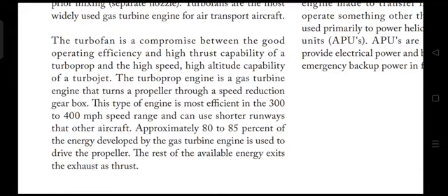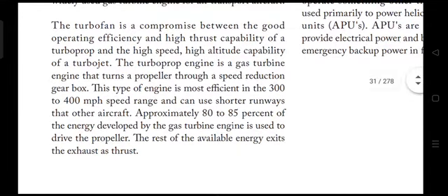These are among the best aircraft for local connectivity, because they don't have to go to a long ceiling altitude. For regional connectivity of 45 minutes to 1 hour, they are the best, because they produce a lot of propulsive efficiency because of that big propeller. Equally, a turbojet is very good for defense aircraft, as I told you, to get a lot of high speed.